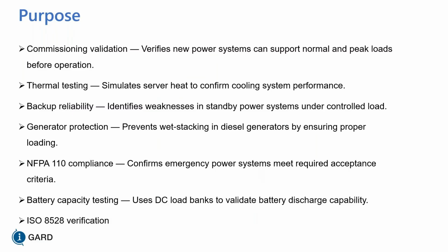This would happen in data centers. So before you start putting all your racks in, you can actually simulate that you're going to put out so much heat and the HVAC system has to maintain a certain load or maintain a certain temperature. And load banks can be used for that. Backup reliability: identify weaknesses in the standby power system under controlled load.